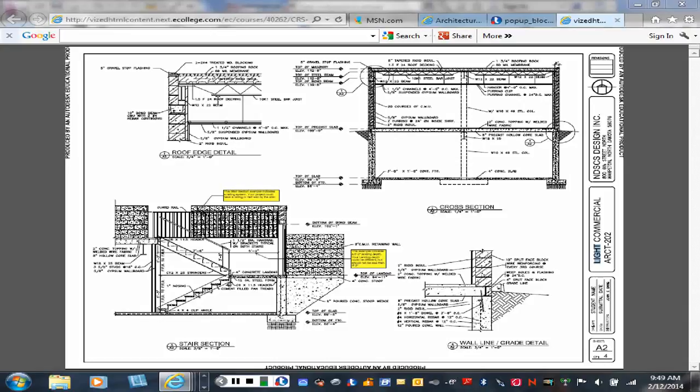And we'll talk about that more when we get to drawing our sections, but the height of the bearing point of a bar joist depends on the depth of the bar joist and the length of the bar joist. But for this building, due to our less than 30-foot spans probably, that height of that bar joist bearing is going to be 2.5 inches. That's pretty common up to a 30-foot length. And then once the lengths get longer than that, that height starts getting bigger. It might be 4.5 and 5.5 and so forth. So at this point, we'll assume that that height's going to be roughly 2.5 inches above the steel beam.